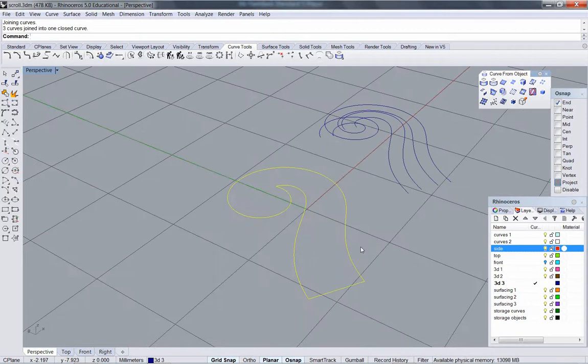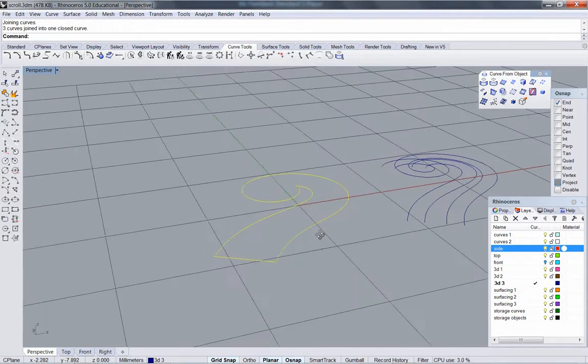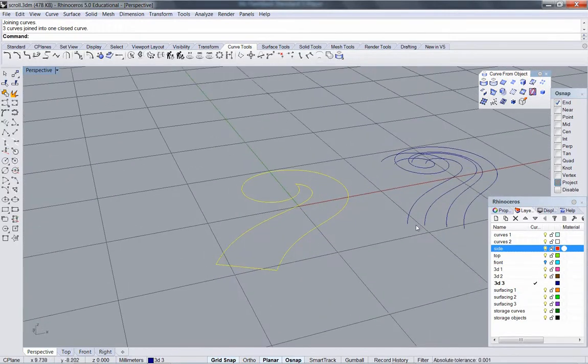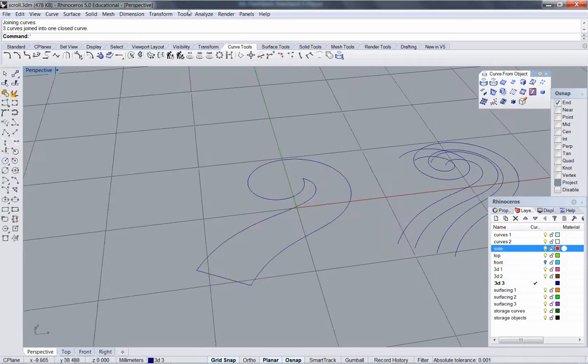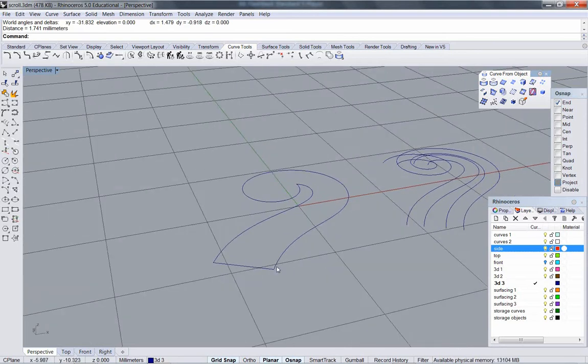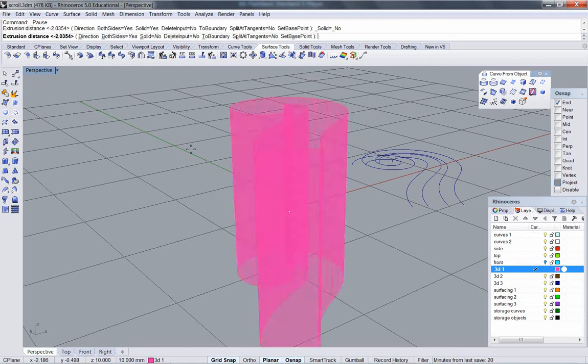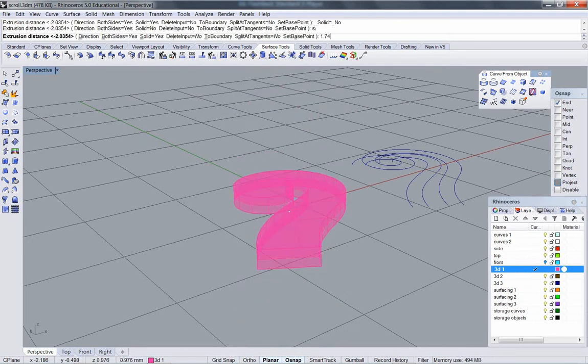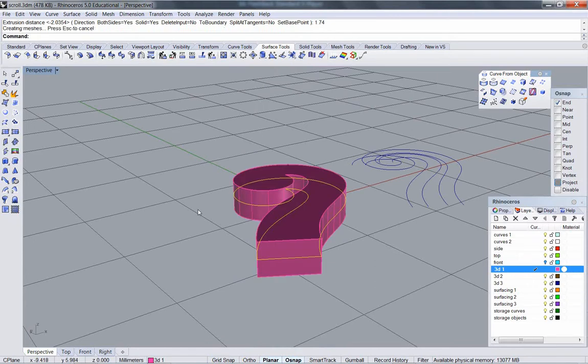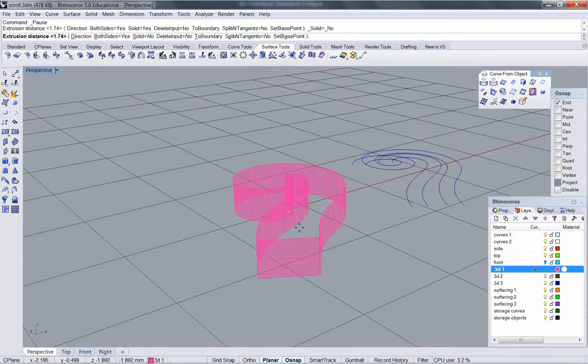My question is going to be how thick do I want to extrude? If I'm going to use a fillet this distance, okay, analyze distance, see what that is. It's 1.74. The thickness of my piece has to at least be that thick so that when the fillet happens, okay, I didn't want that both sides.